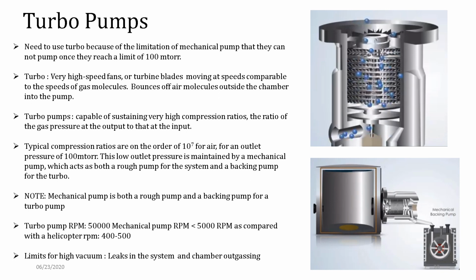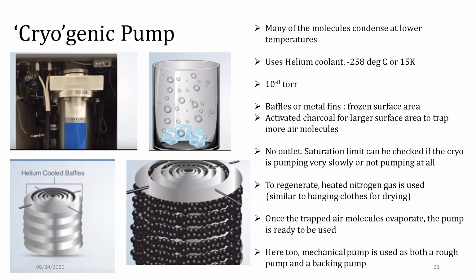And we need to make sure that there are no leaks in the system before we use it, and there should not be any degassing or outgassing inside the chamber. These can literally deteriorate the processes that we are aiming for or the quality of the films that we are looking at. And then come cryogenic pumps.